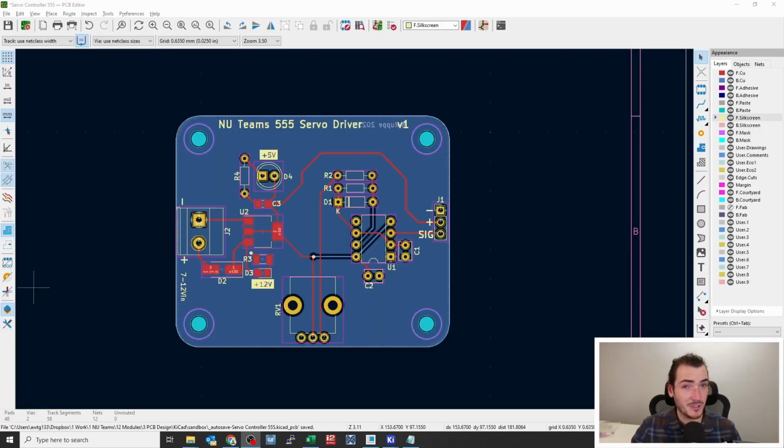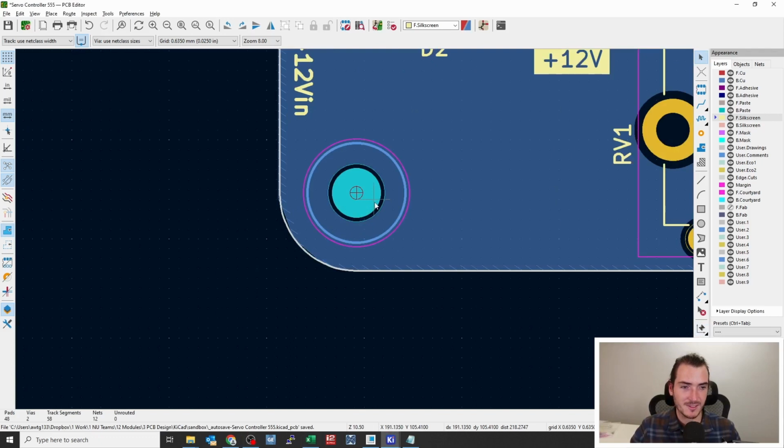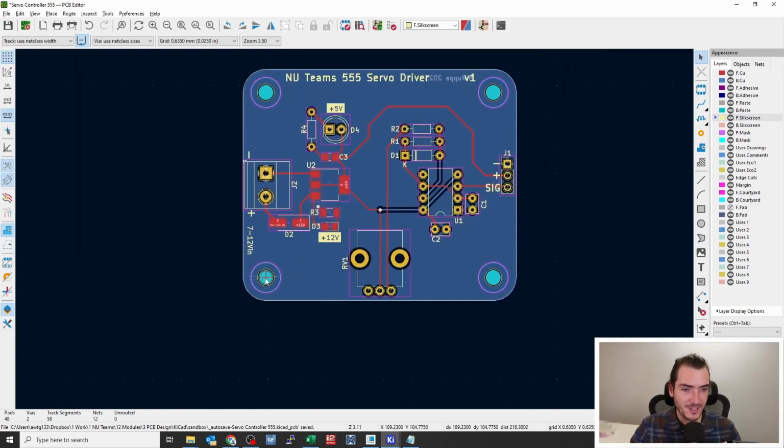Now it's time to export to our favorite 3D software. I'm going to place a drill and place origin. So that's this tool down the bottom here. And I'll place that just in one of the mounting holes. This can be because sometimes exporting and importing 3D models gets kind of weird, and I found that this can be a pretty reliable way to do it. So place that origin. That's basically the 0 for the 3D model. It's what it's going to rotate around.